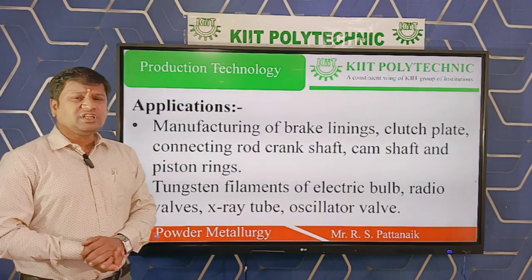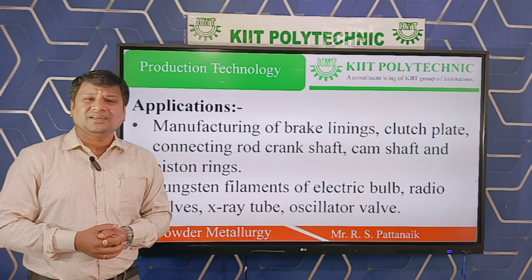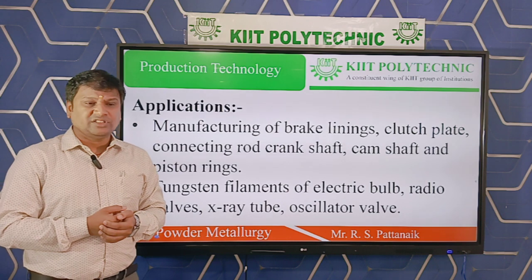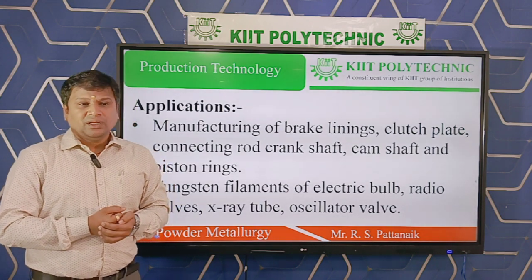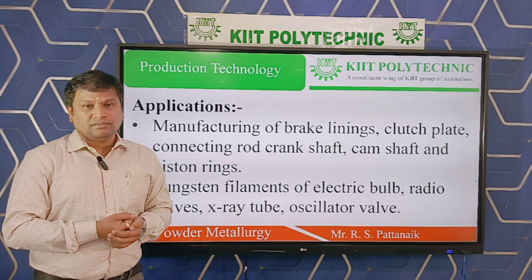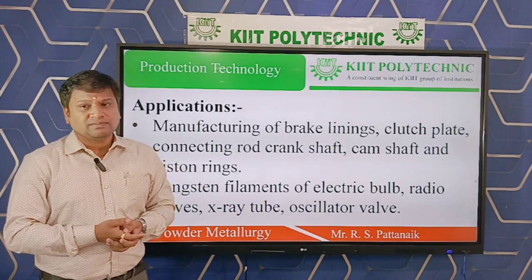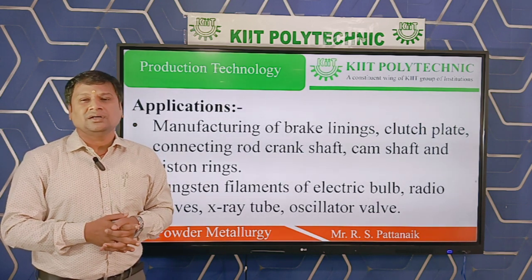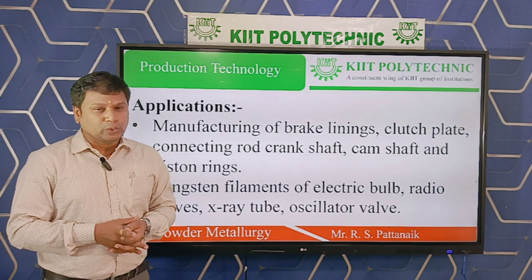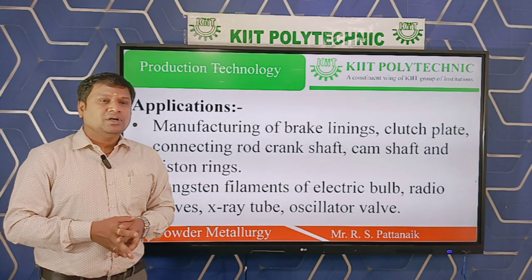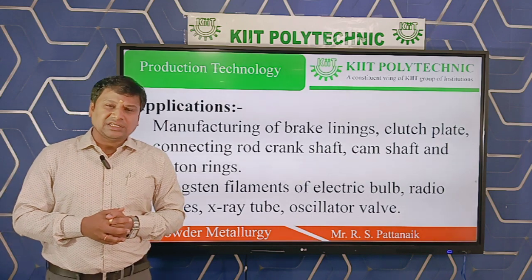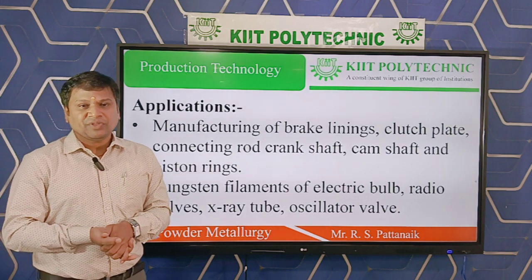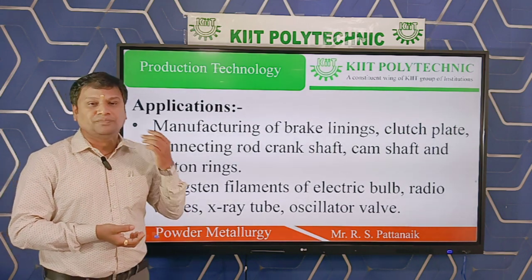Okay, so before the advantages, there are some disadvantages. Okay, like in powder metallurgy technique it's expensive. Okay, then metal powders are very expensive. In some cases mechanical properties as well as physical properties are not so good, like casting. Okay, so powder metallurgy technique is basically limited to small sized parts. Okay, so these are the disadvantages of powder metallurgy technique.